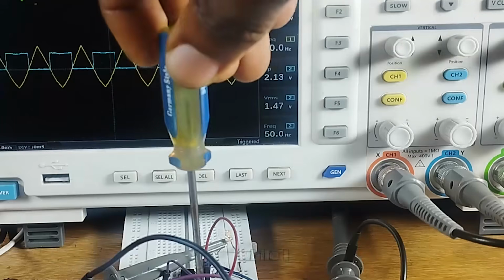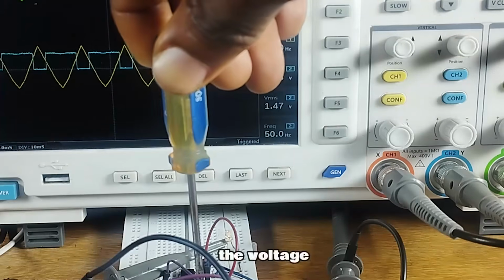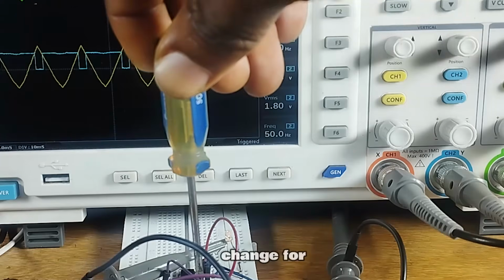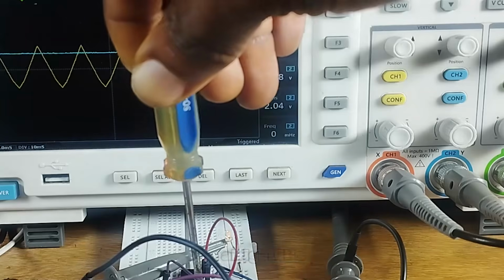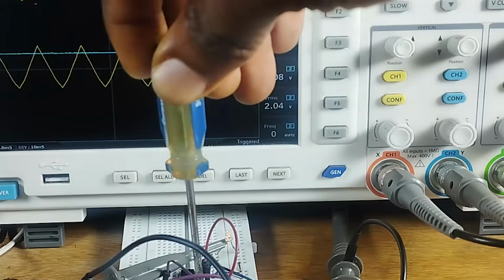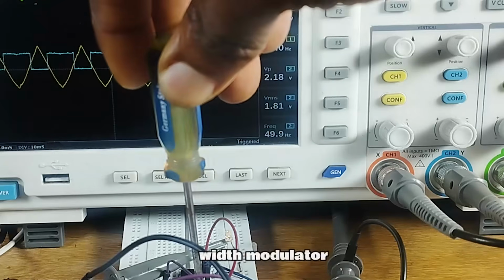Look at the screen. While I change the voltage level, we see we have a width change for the output, and it will change until it becomes a straight DC. Alright, it's no more a square wave signal. Okay, so this is how the pulse width modulator is basically done.